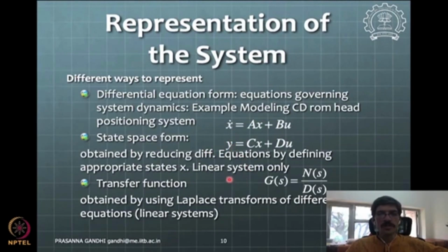In each of these forms there are different tools for control available, but we will consider the differential equation to be the most fundamental form of representation, which will give us some physical insight into the system, and we may use that in incorporating interesting ideas for control. Although you may develop some controllers in the state space form, you can transfer them back to the differential equation form to see their physical aspect or physical implementation or physical insight into that controller.